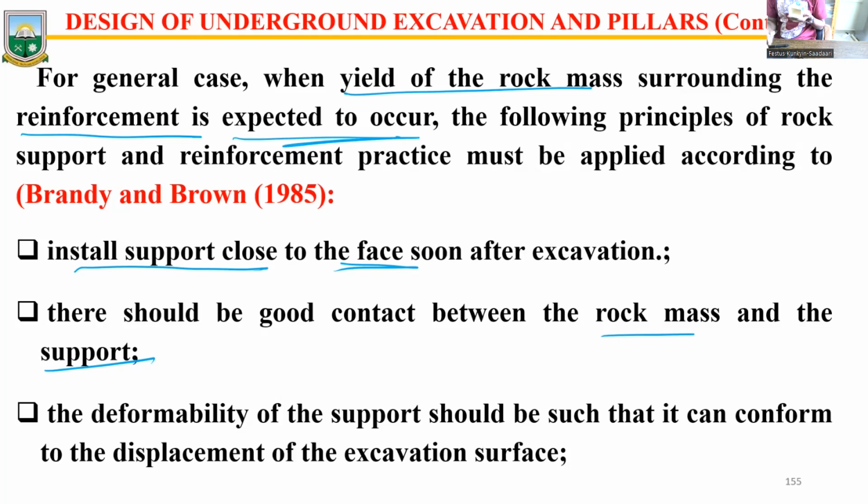But as of the time I did the excavation, I have a pin here, let me use that. Let's say there is some support I will have to provide, where this is the rock mass surrounding this excavated zone I have caused the disturbance in. And with this disturbance, I feel there's an immediate deformation which is going to occur. So instead of this falling off, I decide to bring in a support that will hold it in place immediately. This type of support that has an interaction with the rock as soon as possible is what we term the active.